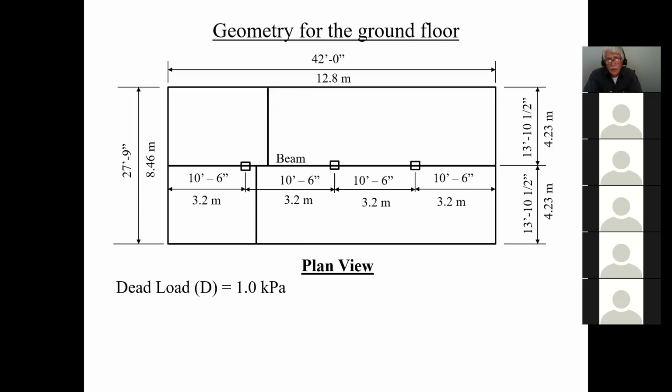But if your MR value happens to be following exactly what your MF value is without the weight of the beam, well, I would see how much of an impact that might have on my final design decision, okay? So that's alright for now, but in theory, I should make an allowance for the beam and add it to my dead load, but I haven't done that.